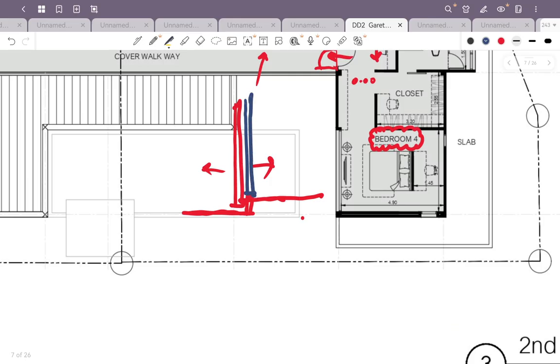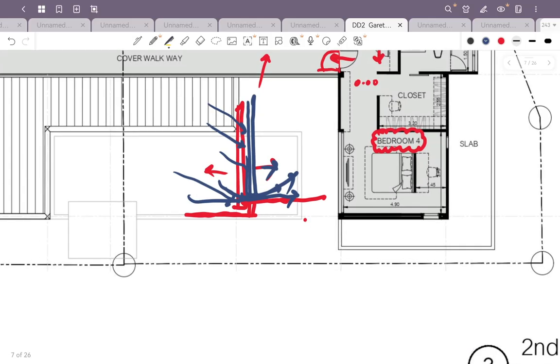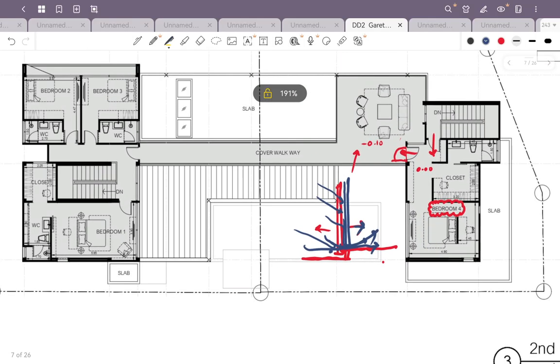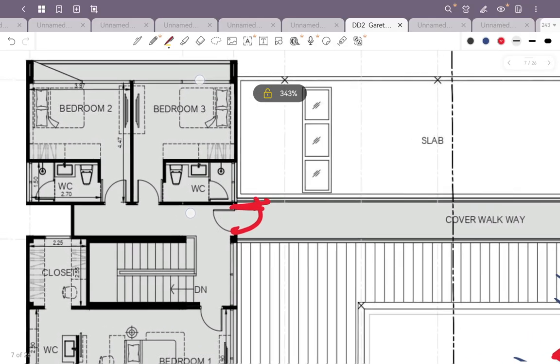Now you can open inside, but when water or something goes to the door here, it comes down to this, and the wind blows the water inside the house, and also dust and insects go inside, because you don't have an overlapping layer between the door and the floor. Okay, so that means this one also needs to open outside like this.